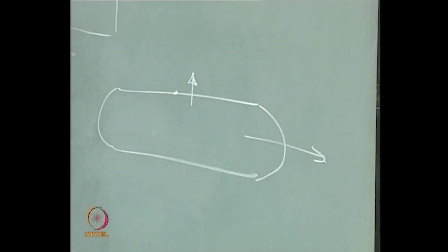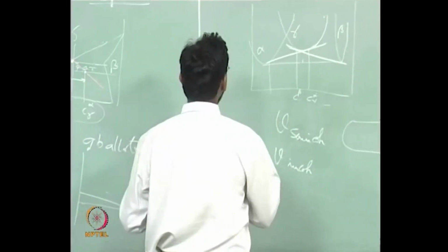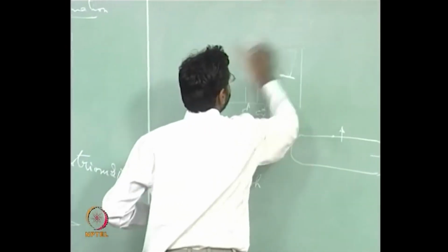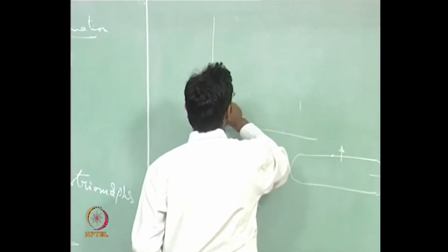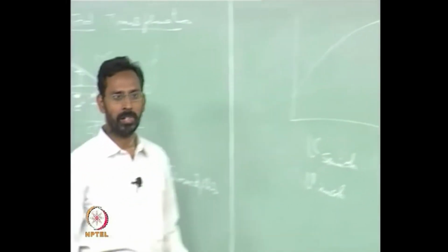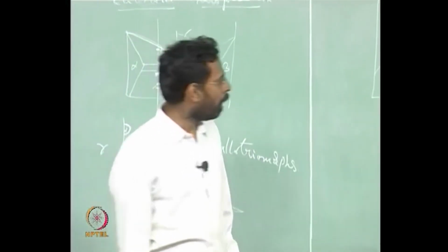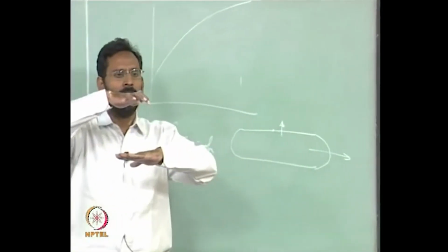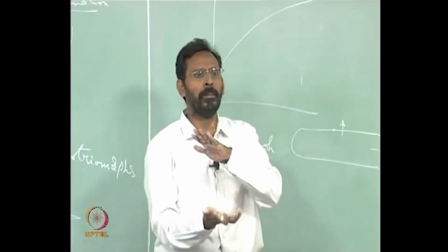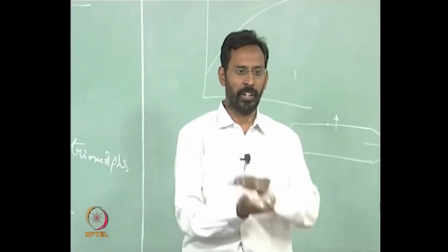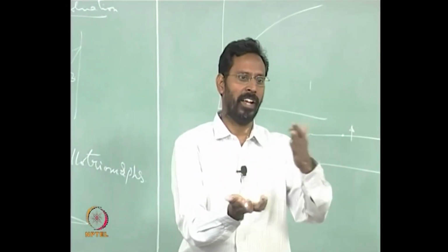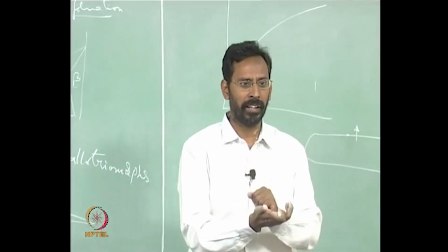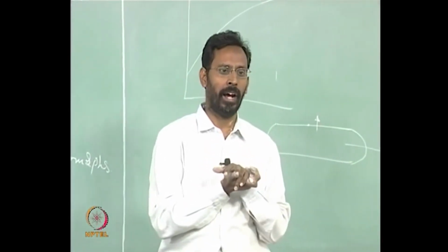So as a result, you see that at higher temperatures, if I plot the ratio of, yeah, because whenever you are talking of coherency, coherency is on any particular plane. When nucleation is taking place, a plate is nucleating on a matrix, let us say a theta double prime or something like that, nucleating on an aluminum matrix.